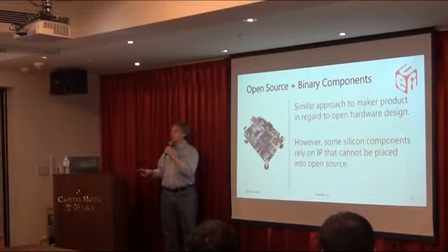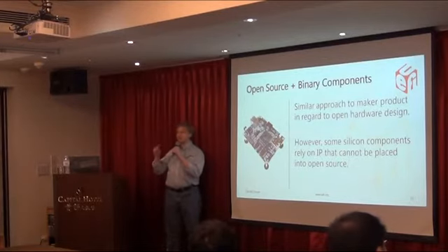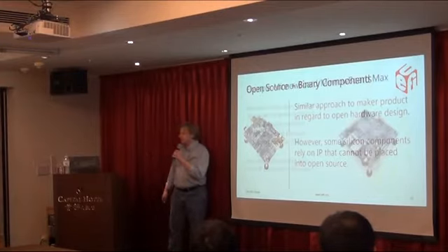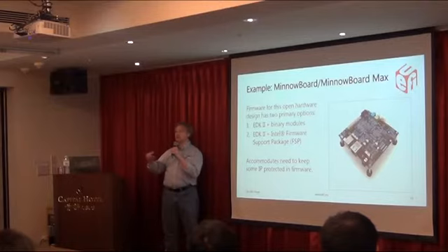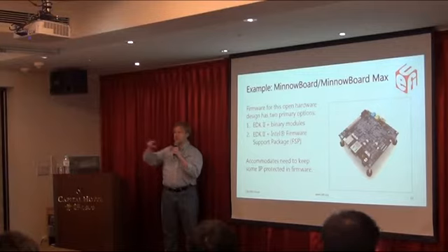However, if we design an open hardware board and we want people to use that chipset and that platform as a reference, how do I combine that with open source? Well, the answer is that you take the things that are in closed source that require an NDA to look at, and you package them as binaries, and you wrap the open source around that. There's two different ways to do that. One is to do it a little bit more like EDK2, where you take the individual PEIMs or DXEs, build them as binaries, and shove them into an FDF file, and they become part of the binary load of the firmware. So you have a lot of open source, and then occasional points where you go to a specific PEIM or DXE component, and that stuff's closed off.